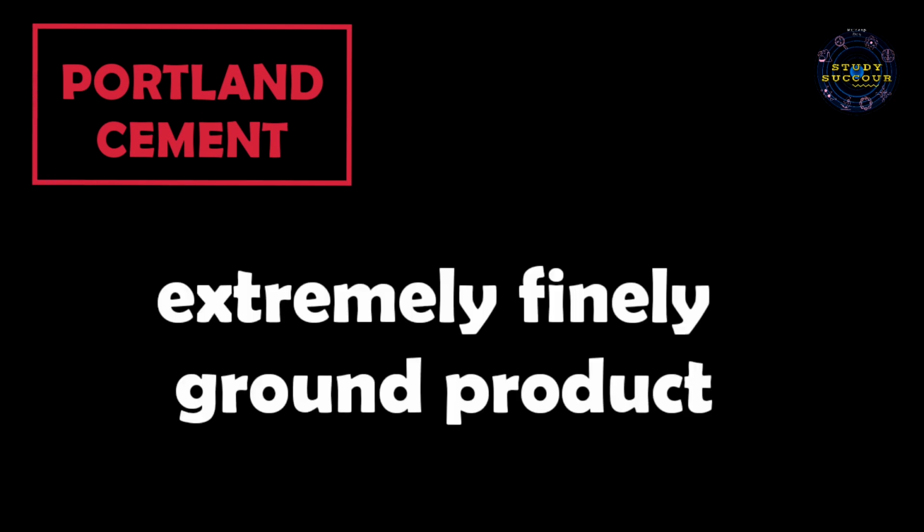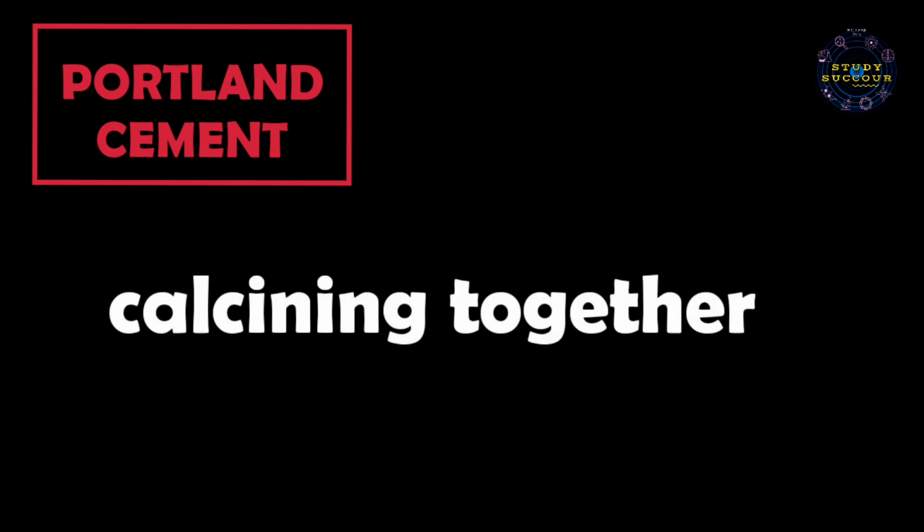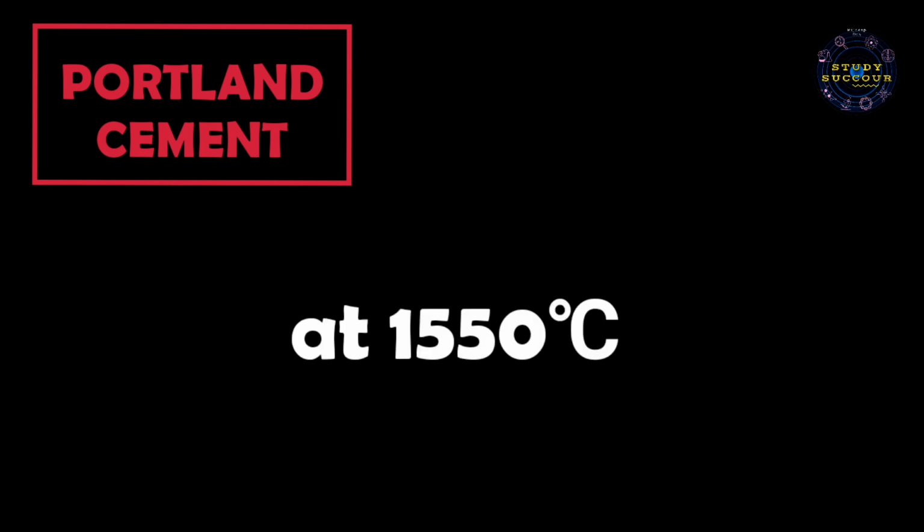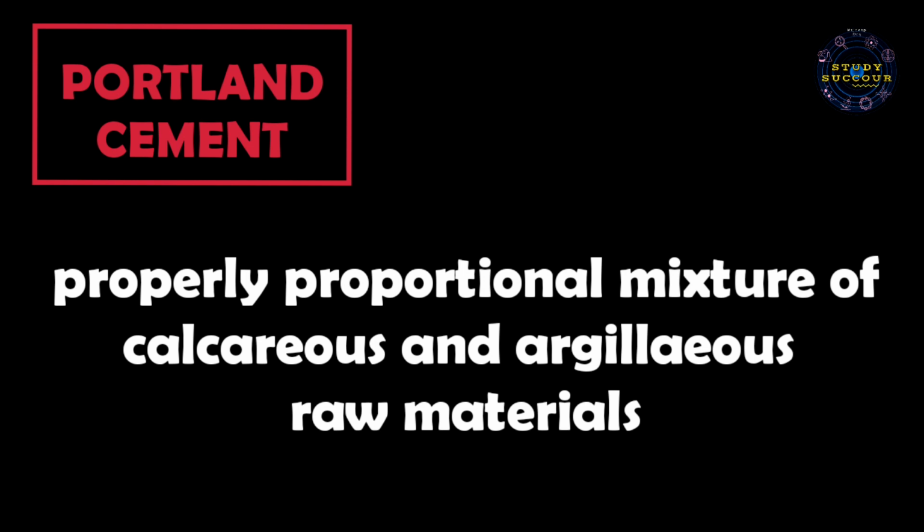It has been defined as an extremely finely ground product obtained by calcining together at about 1550 degrees Celsius, an intimate and properly proportional mixture of calcareous, that is lime containing, and argillaceous, that is clay containing raw materials.